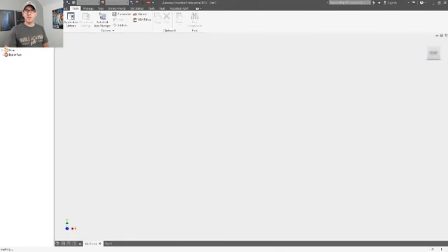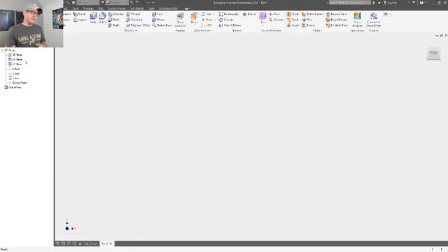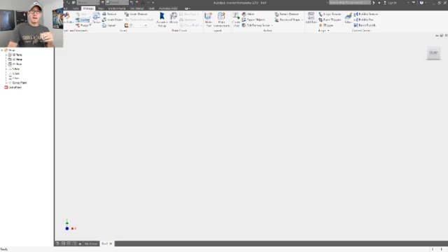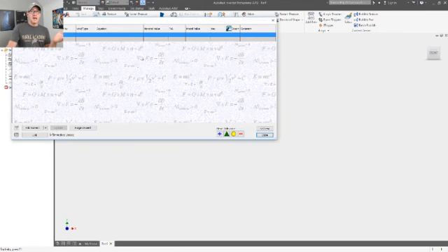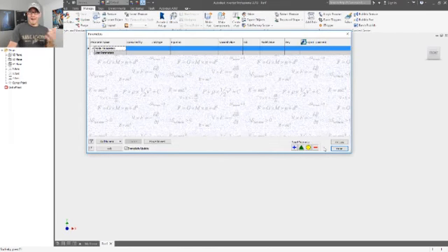So a couple ways you can do this. The first thing, when you're doing parameters, everybody thinks you have to do parameters ahead of time, where I have to go in and create a parameter called length, another one called distance, another one called height. And you could do that. Like if you wanted to, you could come in here, go to the Manage tab, go to Parameters, and you could actually start to add and define all the parameters that you want to define as you're going. That's totally fine, and that's definitely the way I would work if it was a consistent parameter that I'm using all the time when I'm creating geometry.